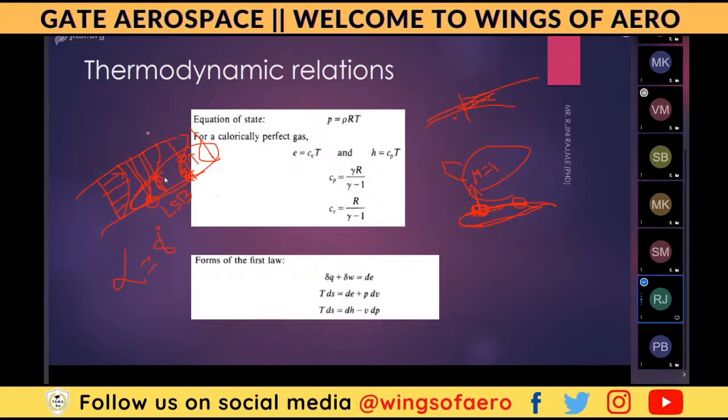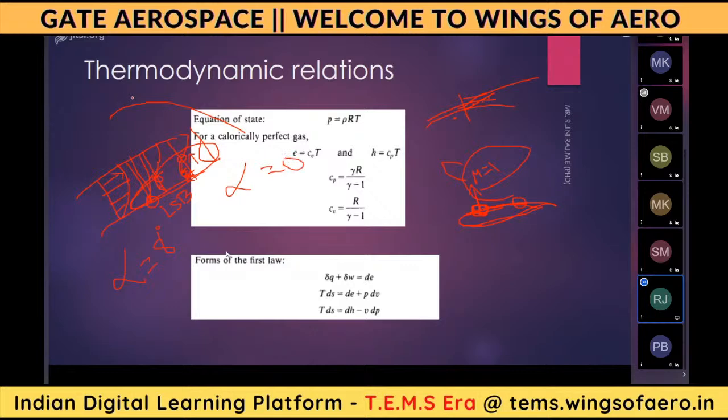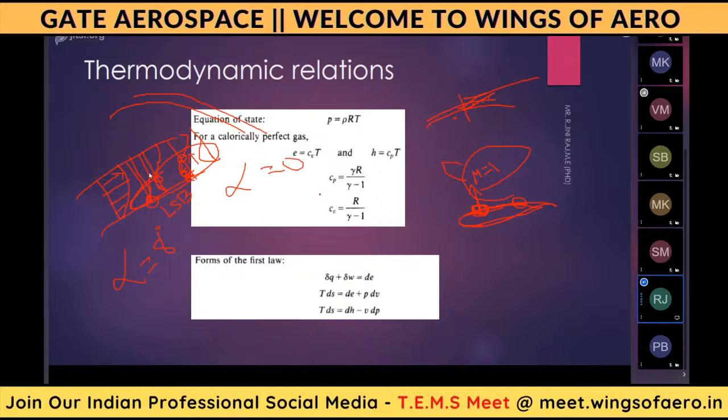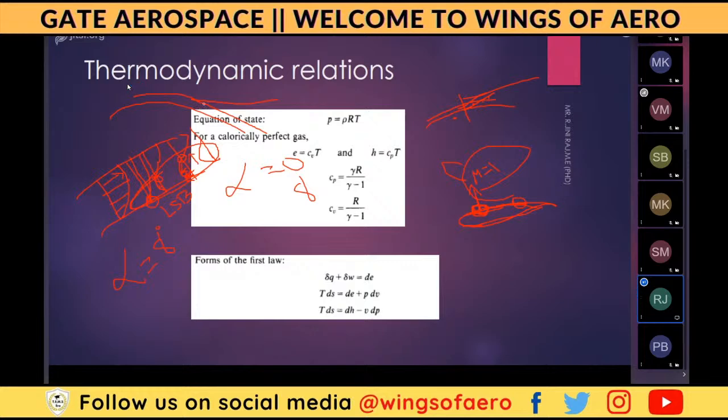So the separation bubbles, this is the aerofoil, the top surface of the aerofoil. When the angle of attack is 0 degrees, the flow will be fully attached. When it goes beyond 8 degrees, what will happen? From the trailing edge region, the separation starts somewhere. The flow separates like this.